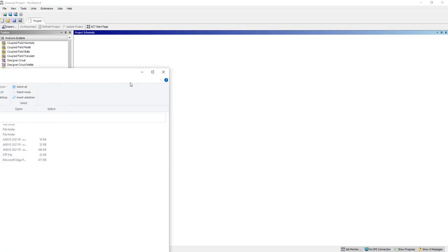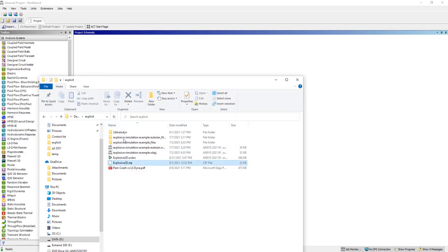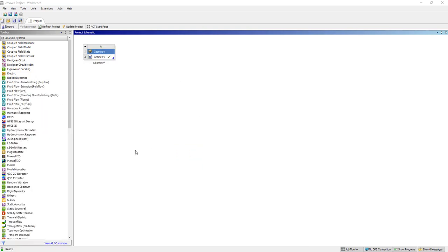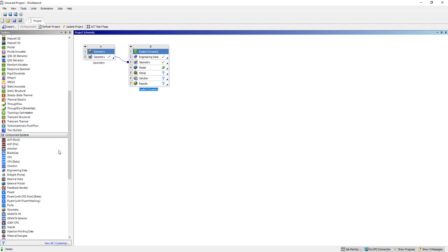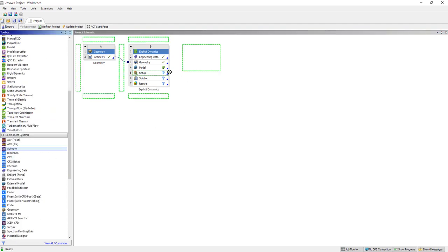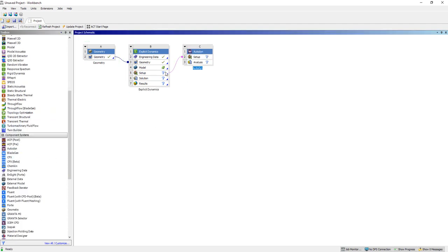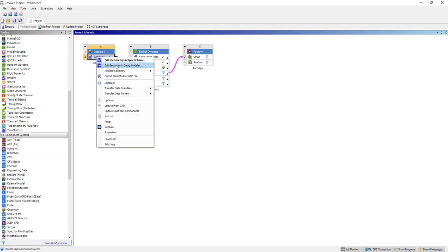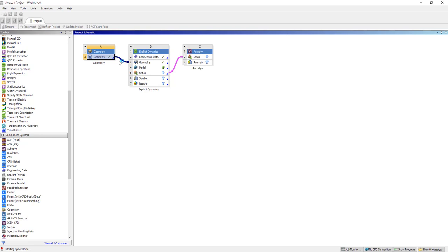Let's get started. So we're going to grab a 3D step file into our Ansys Workbench environment. The 2D analysis in the Autodyn for multi-material Euler analysis is not available in the standard explicit dynamics. But we can use it to set up our model and then finish the simulation with Autodyn by connecting the model up like this. Let's go ahead and edit the geometry in SpaceClaim.